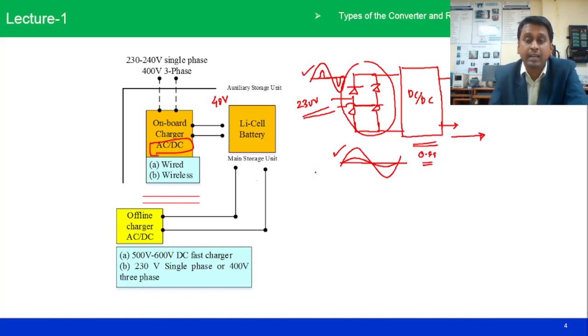Now the charging time of this kind of system is quite slow, because we cannot regulate the current here. So to regulate the current there is a requirement to change this DC to DC stage. Again, there is a requirement to increase the voltage level, and an extra current loop is required to regulate the current. That is generally known as the fast charging system. If fast charging systems are used, then the charging time can be drastically reduced.